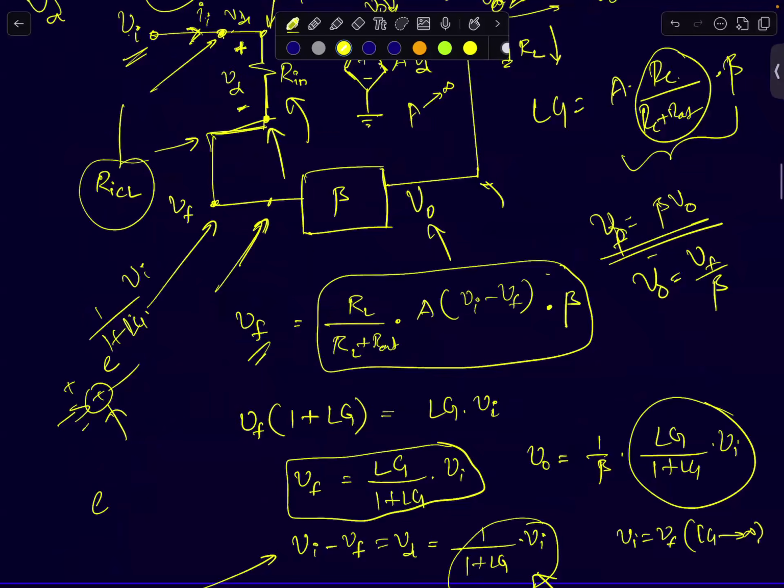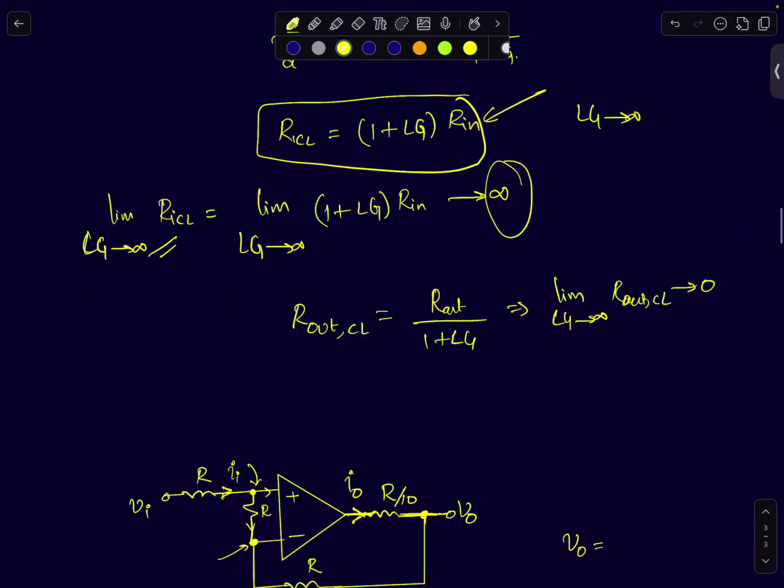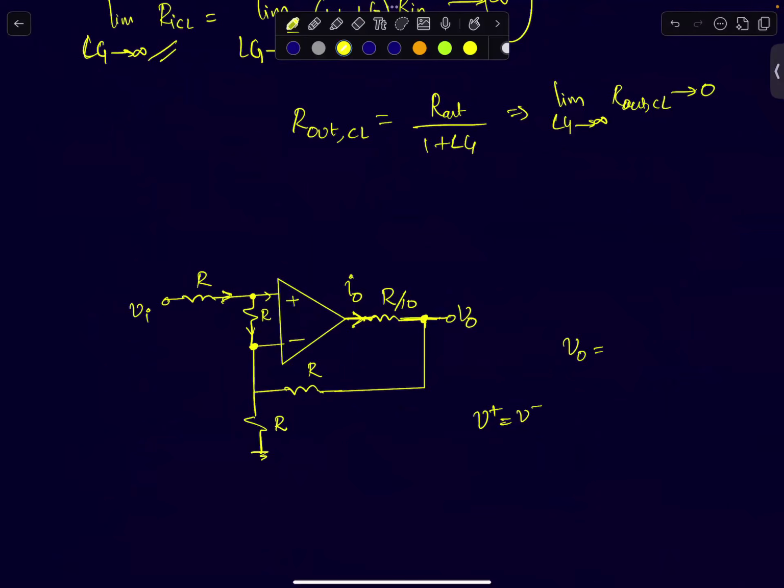So now if I go back to this circuit, immediately look at this. This is the op-amp. It is a negative feedback. There is no doubt about that. You are taking the output signal and feeding it back to the negative terminal. Since you are feeding it back to the negative terminal, now I'm interested in finding out what will happen to these two node voltages.